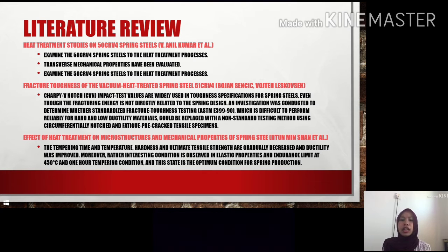Moreover, an interesting condition is observed in elastic properties and endurance limit at 450 degrees Celsius and 1 hour tempering condition, and this state is the optimum condition for spring production.